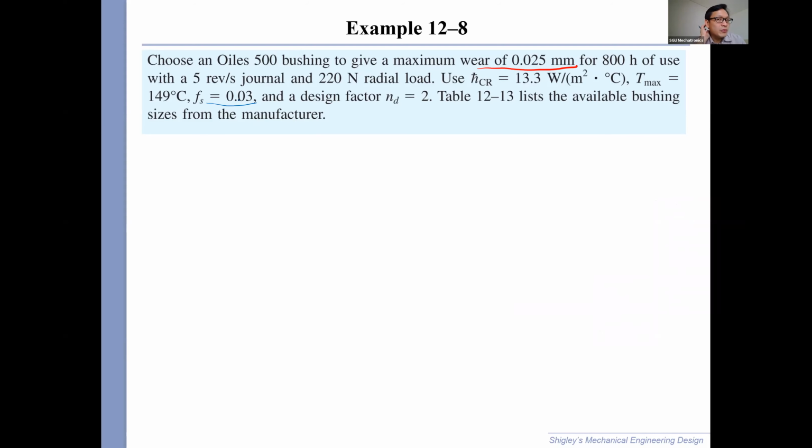So the way you will use this design factor is simply multiplying the load with a factor of 2, just like stress concentration or other applications where we have an increased margin of safety. Right? That's what design factor is.